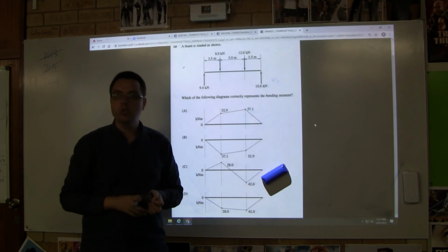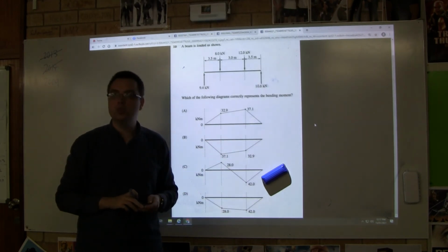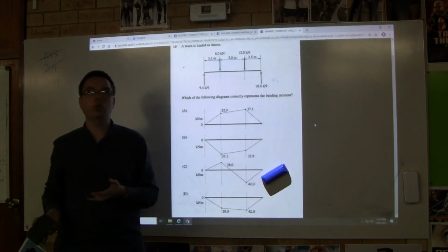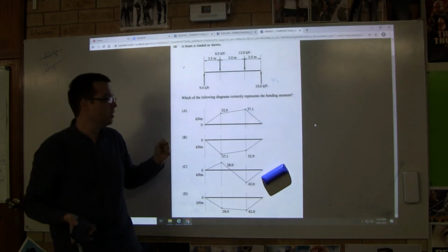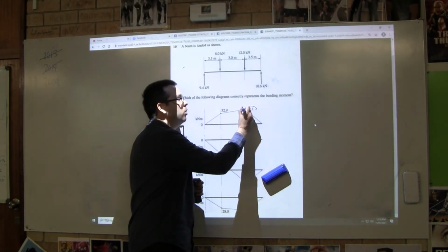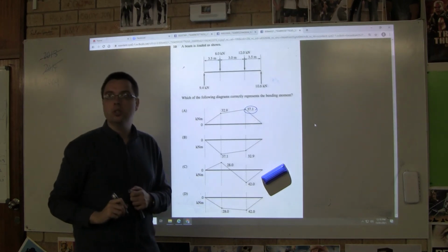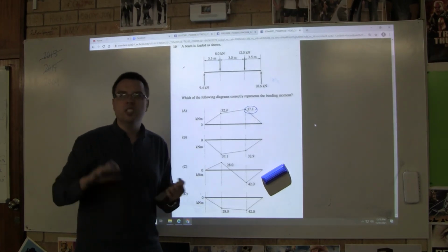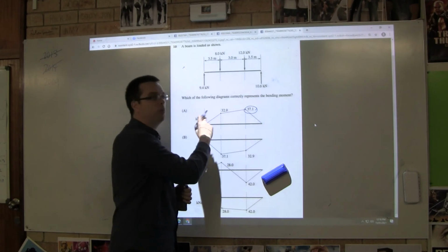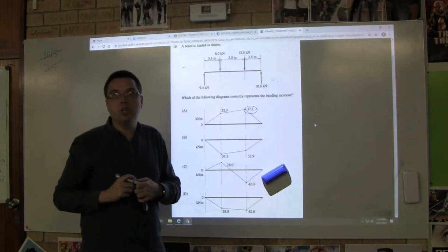We've just covered 3 questions, and we've introduced how to use bending moment diagrams and shear force diagrams. We also know why we use them. Just to remind you, the key point is that we use this for our maximum bending moment. Typically, we're not interested in the bending moments at lots of locations. We're usually just using it to find the maximum bending moment.